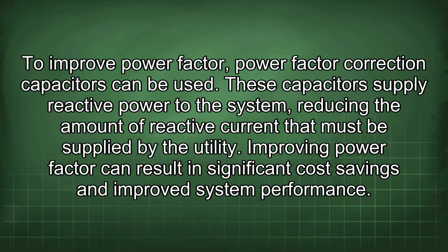To improve power factor, correction capacitors can be used. These capacitors supply reactive power to the system, reducing the amount of reactive current that must be supplied by the utility. Improving power factor can result in significant cost savings and improved system performance.